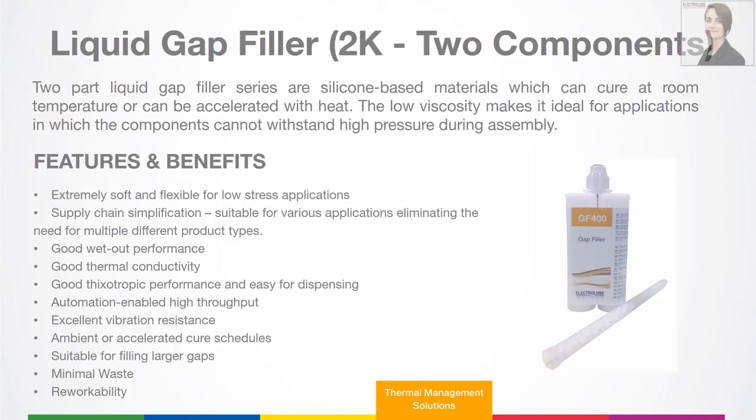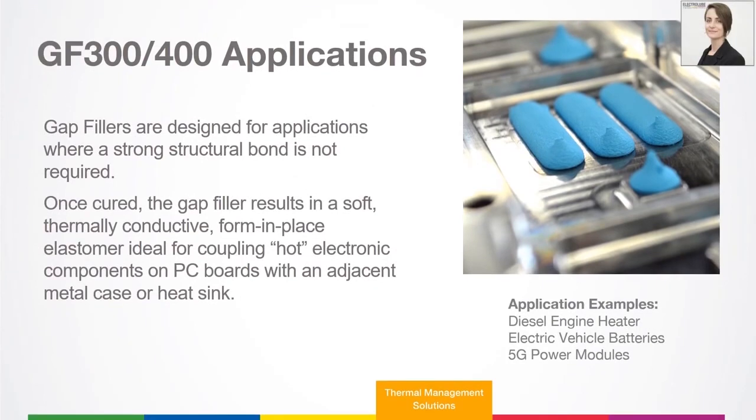They are designed for applications where a strong structural bond is not required, so they're not considered to be curing, bonding thermal interface or gap filling materials. If you consider them more like a gasket, a form in place type material. They're designed to have little contact resistance at low pressures. So the gap does need to ensure that you get some compression to maximise performance. But you're not looking at high pressure applications here.